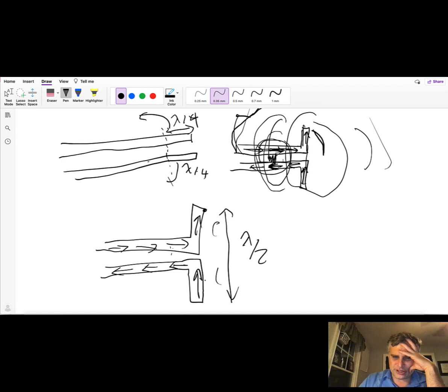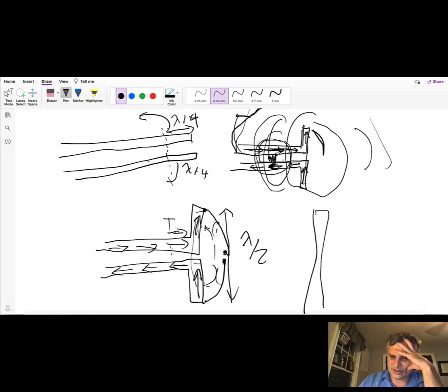I have zero current at the end, rising up to a maximum peak current of what we'll call basically I into the antenna. And same on this side. Zero at the end, peak at the middle, symmetrical. You'll notice that when I bend these two back from the open circuit configuration, they're now all aligned. So really the radiating part of the half-wave dipole is essentially a piece of metal in which a standing wave of current has a sinusoidal arc, 1/2 wavelength long.